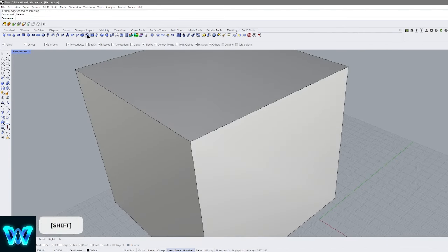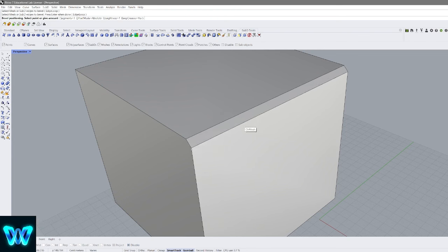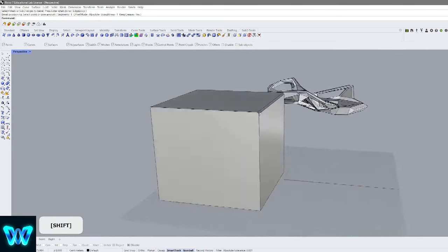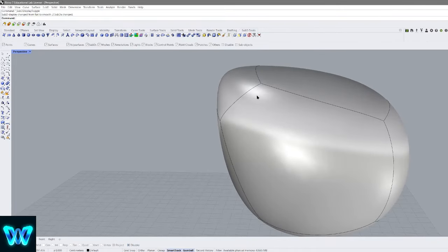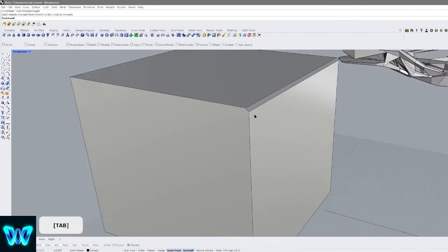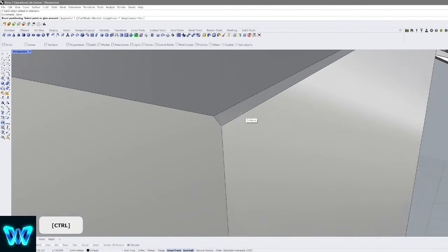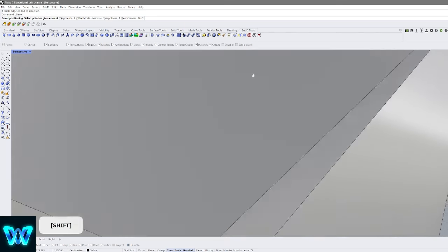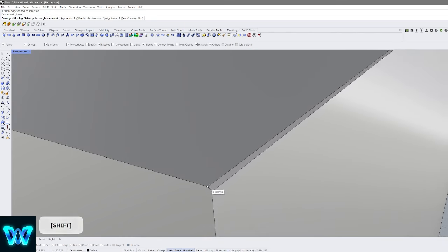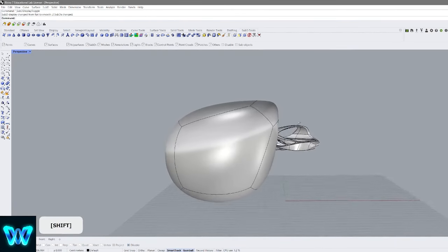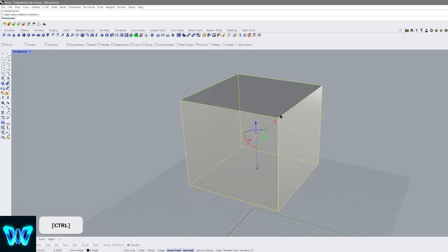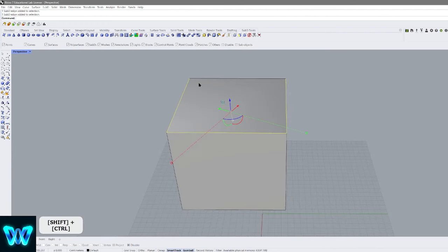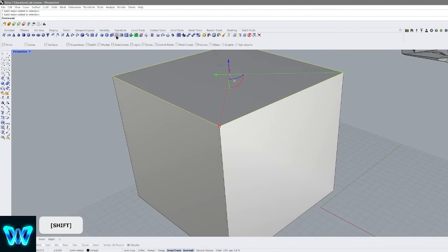So the moment I create a bevel SubD, and I take this and I add this, you would expect that it adds more curviness, but it does that on the polygonal form. On the non-polygonal form, what it adds is less curviness. It actually brings it back to a more corner state. I can do it again and do it very, very small. The smaller it is, the less there is to curve. And you will see that it's not that noticeable. But if I do, for example, all four edges, and I bevel it.